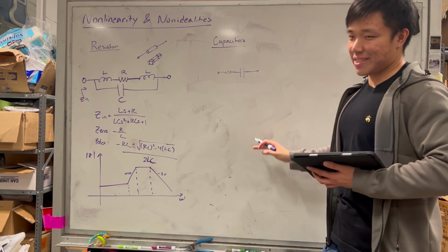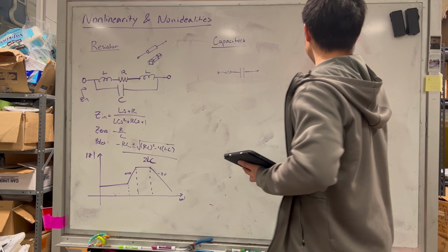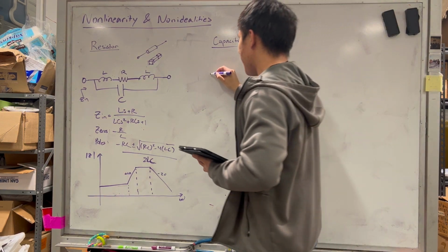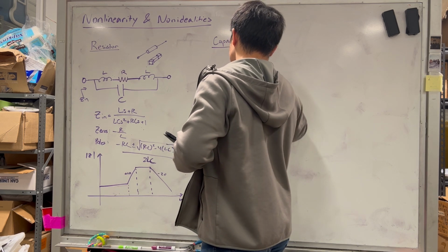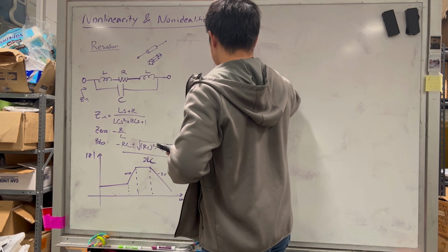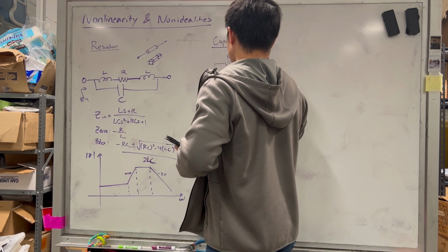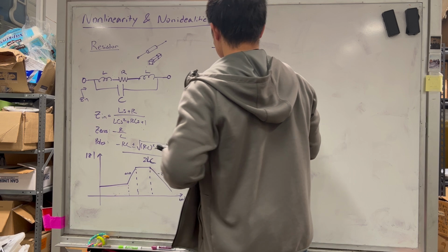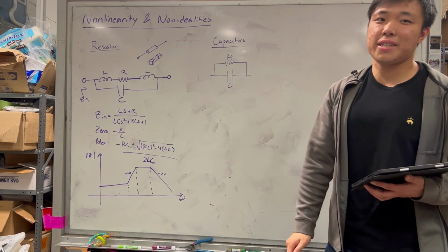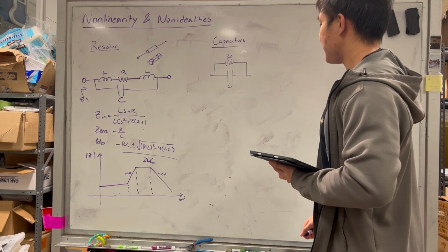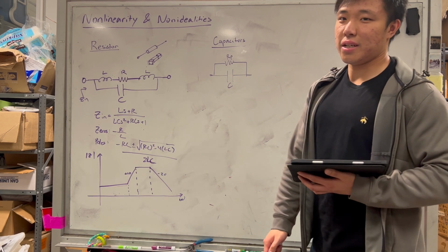But is that the case? So no, that's actually never really the case. It might be really small that you can't really see it, but you actually have some parallel resistance, call this RP, that spans the capacitor. And this model is kind of like the dielectric leakage that you have in your capacitance. And typically this is ignored.